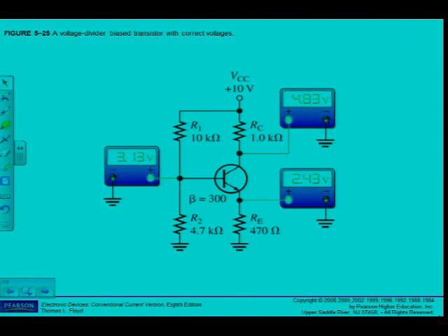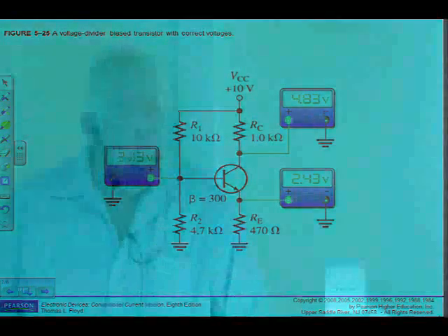We take a value of R1 as 10 kilo ohm, for instance. Most probably 10% tolerance resistances will be used. So you can see that I make some assumptions in my calculations that of course will not be true when I do it practically, to go and measure these voltages. But anyway, let's have a look at the faults discussed in this section of the book.